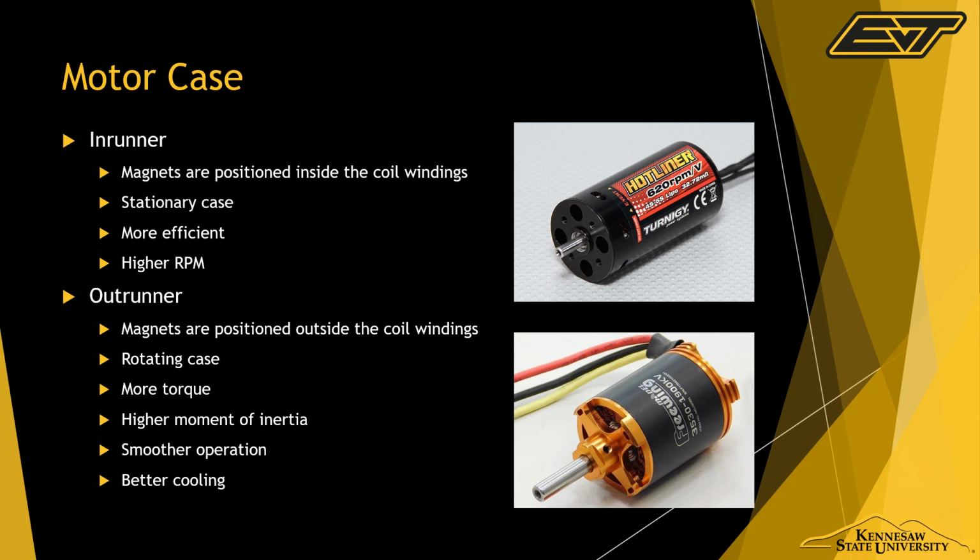Now, in-runner motors typically have RPMs close to, I don't know, 8,000 might be the minimum. At 10,000, you could probably get 12,000. There's a lot out there. If you've done a lot of searching on motors, you probably know what I'm talking about. But in order for us to do a gear ratio for, let's say, 10,000 RPM, we're going to have a gear ratio of 4:1 or higher, which means that we can't go just from one sprocket to another. We have to actually use a gearbox.